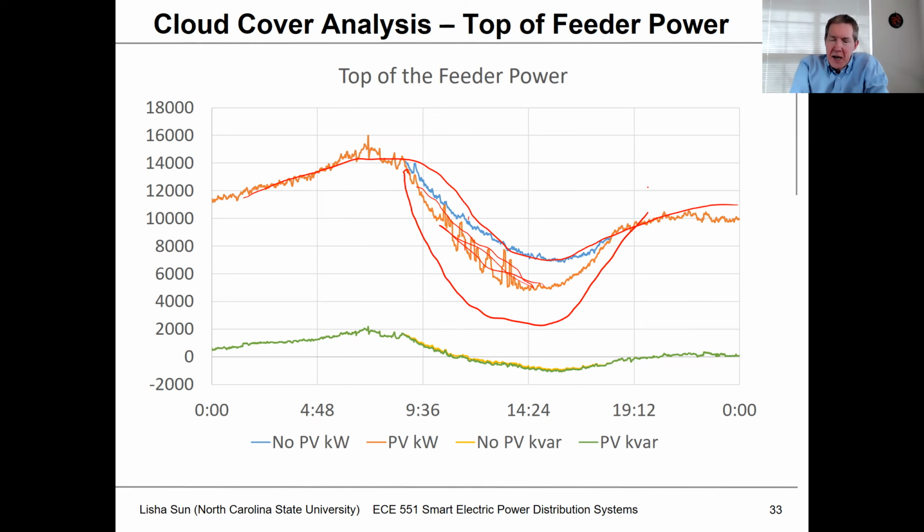In real systems, we actually see cases where we can have so much PV that the flow actually goes negative. And so the issue we run into, if that flow really goes negative and then the PV goes away, is that consumption swings back to positive again. And this is where we run into a lot of issues with regulator control and maybe protection, things like that.